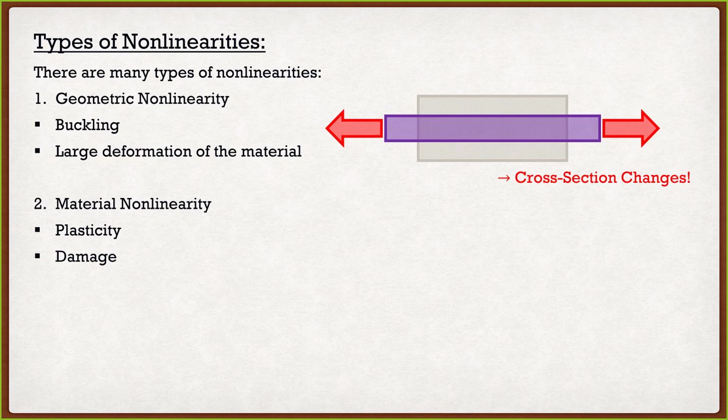Second one is going to be damage. And the best example I give with damage is concrete. And one of you guys mentioned the cracks in concrete. Once I crack concrete, it stays cracked. When I push it back, of course it'll make contact with itself again. But those bonds that I once had, they're not coming back. It's gone. So that's something we have to take into account.